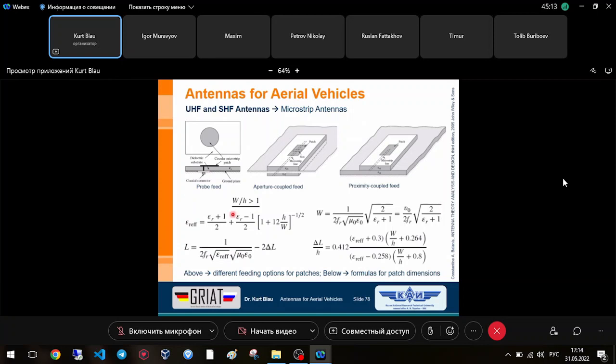But the dimensions of the antenna, here we have a circular patch, it's clear, have to follow the rules of what happens on the substrate, so we have not the free space regarding the dimensions. Here we have to consider the dielectric material with the relative permittivity epsilon relative.